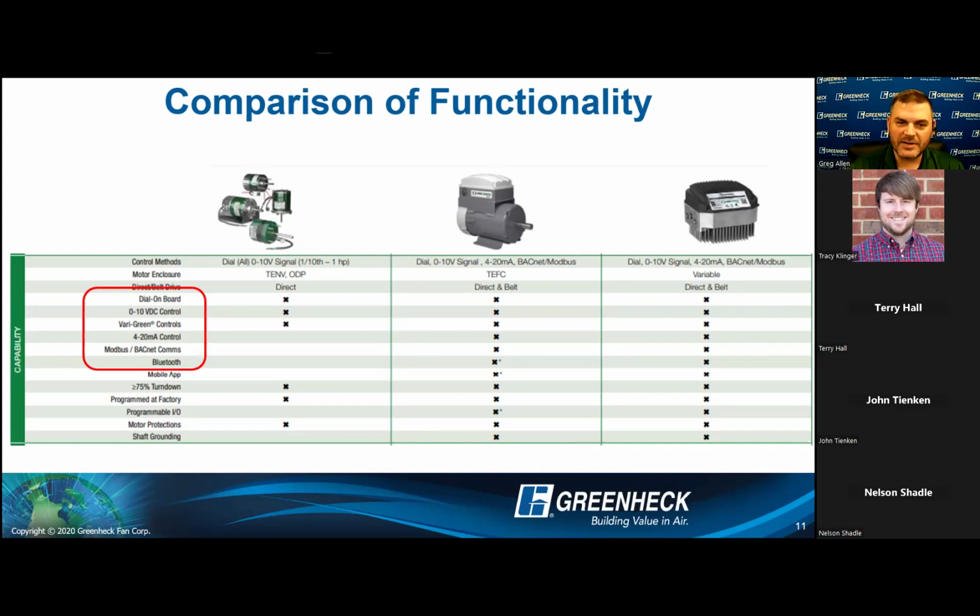So this information is going to line up and say, hey, this device sends or receives these types of signals. And you may find it's a common product, but there are variants of it. And that variant, which is usually defined by the model name, it gets longer and longer. That is actually saying, okay, this is the 0 to 10 version. This is the wet input version.